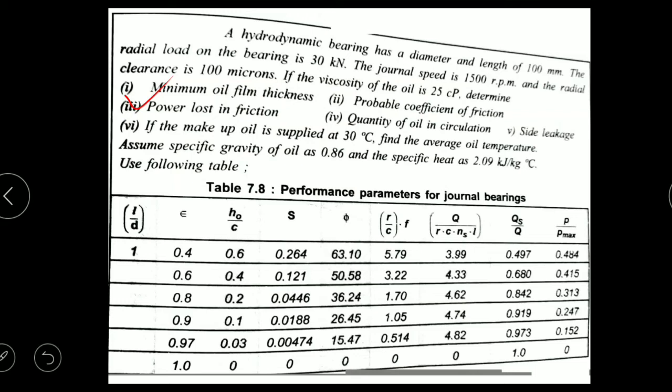Okay. Then the quantity of lubricating oil. Quantity is nothing but Q, flow rate. Correct? Quality means viscosity, and viscosity is given. So quantity we need to calculate. We know the minimum and maximum limit from the chart, so take a reference of the chart. And the Q value: Q is situated in which equation? This equation. So for Q I will have to take, see carefully, 4.33 and 4.62.